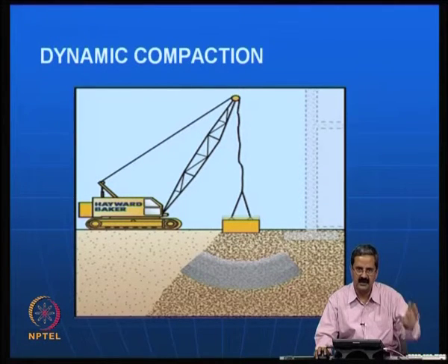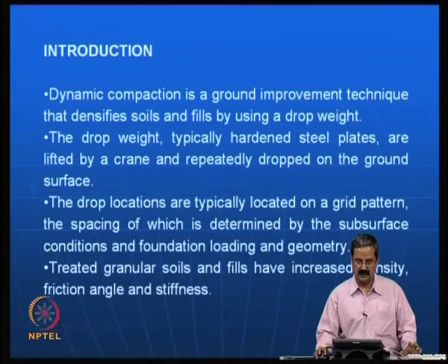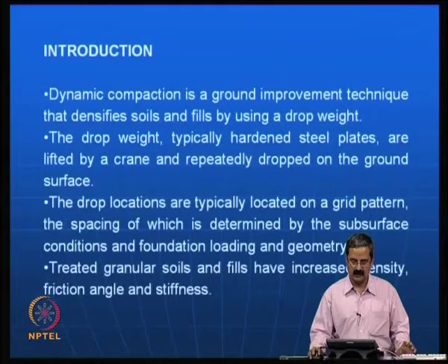From that potential energy, whatever energy gets transferred to the soil, there could be some energy losses here because the soil itself is a damping material. So the soil becomes quite strong, and although it may not receive the full energy, the energy that is transmitted to the system is good enough for it to perform as a very good material, wherein the settlements could be minimum and the bearing capacity is very good.